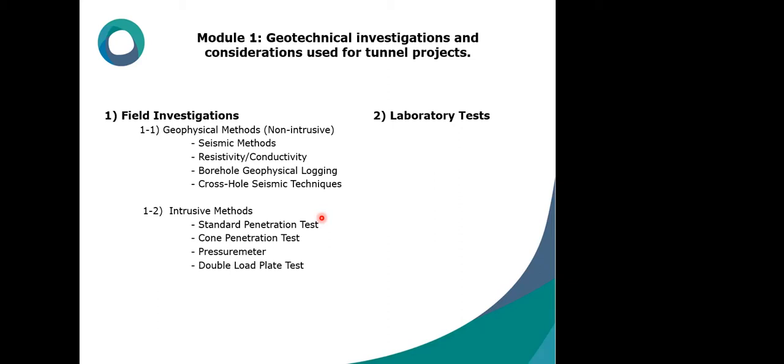Here, we will concentrate more on field investigation because although these methods are more expensive, they usually result in more economical and optimized design. In situ techniques, in spite of their resulting high costs, could be cost-effective for projects in general. We will learn intrusive and non-intrusive in situ methods, and the parameters and information that can be attained by them. Geophysical ways are very beneficial in line tunnels where we don't have access to the whole length of the tunnel at the beginning of the project.